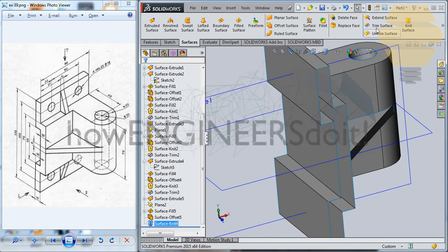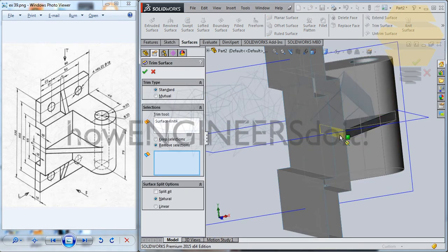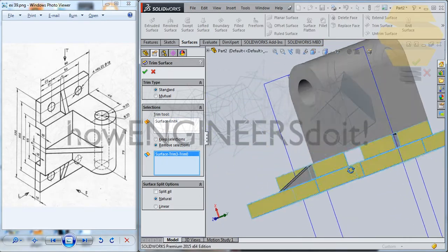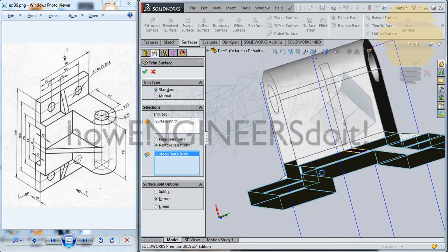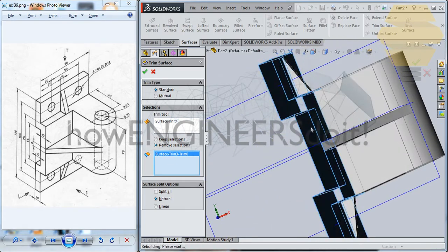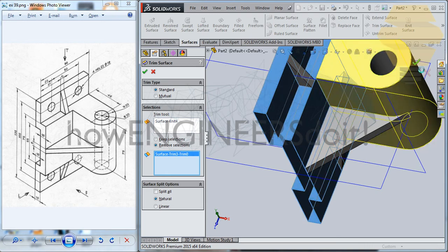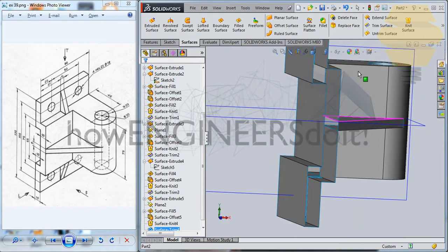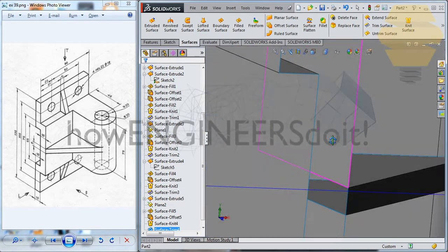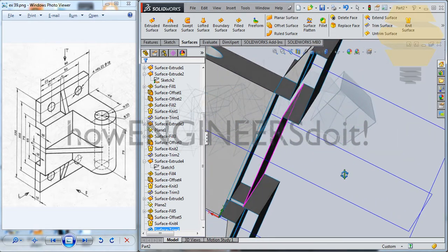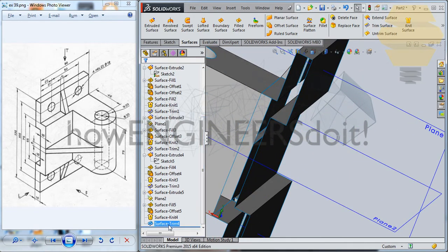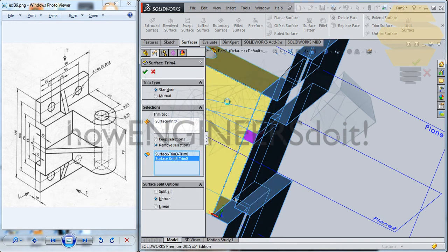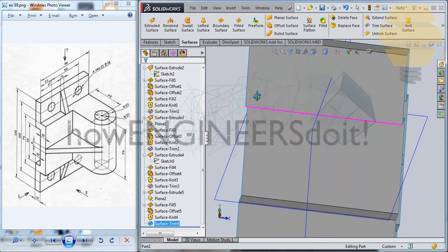With the surface knit 4 selected, you can go inside and just take this portion, this little guy here, and go for tick mark, and that portion is removed. Okay, I think if I just edit feature, could have also removed this part. So this continuous surface is being created there.